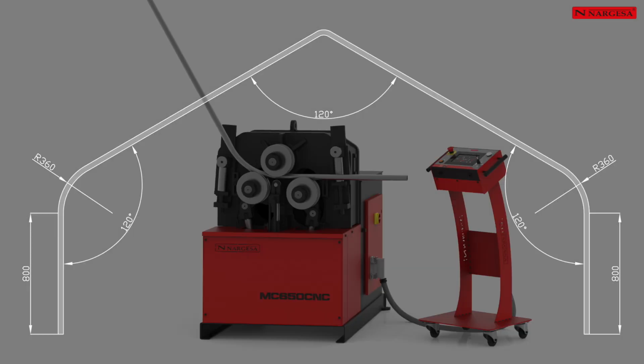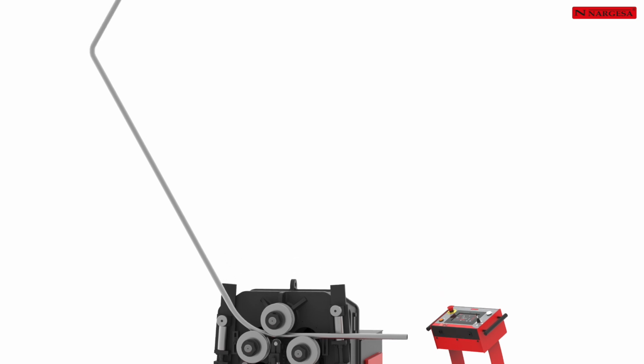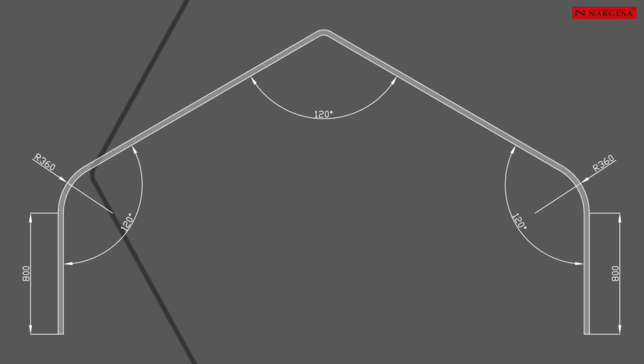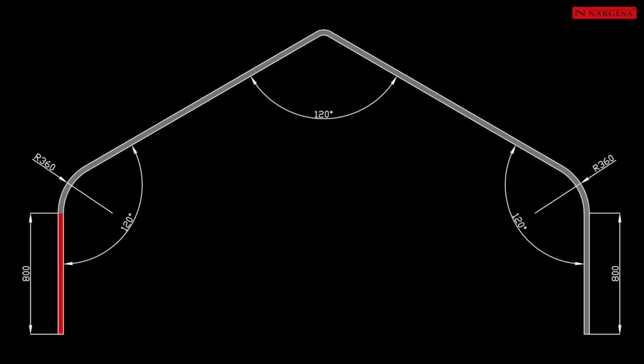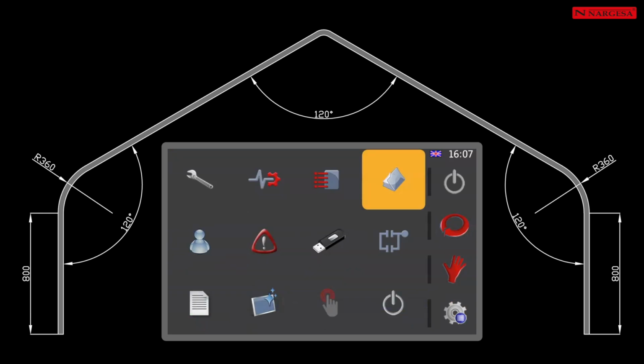When there is not enough height to make a piece all at once, you can order each bend so the finished piece does not exceed a certain height. Begin by creating the first of the legs, then the other, and finally, shaping the upper vertex. In manual mode, access the menu Programs.